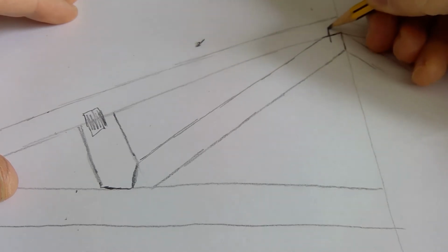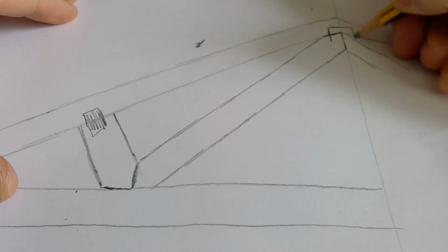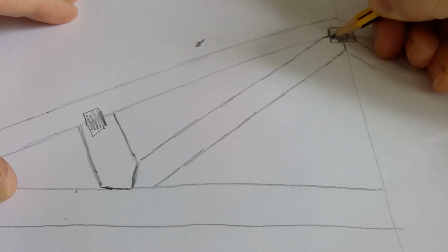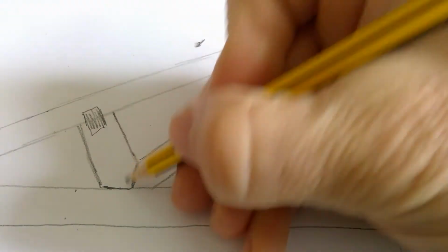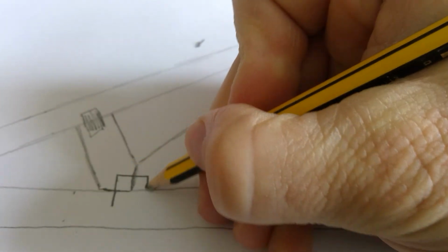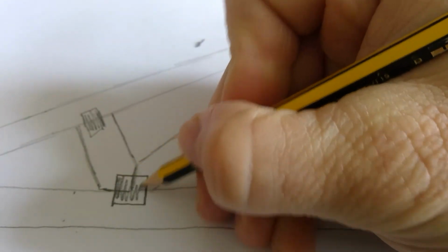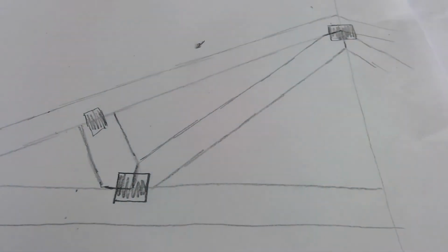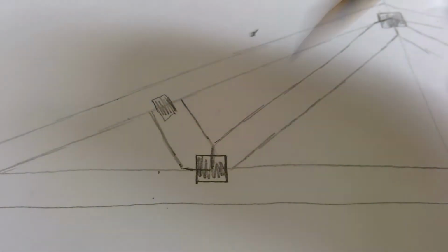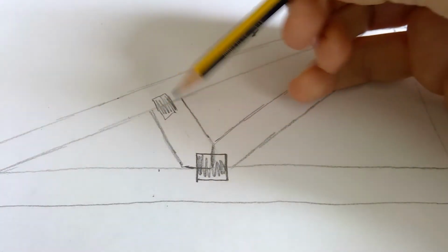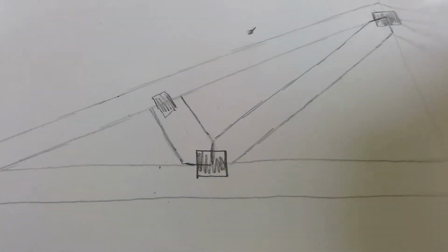Now there's a nail plate that goes into place like this. They have a bigger nail plate for these top pieces. Again, just simply look it up on Google if you want to get that understanding. That is there. And there'll also be a nail plate covering these three pieces here, which fixes it into place. There's a nail plate on both sides of those. Okay, so don't worry too much about angles and positions. If you get it roughly like that, you're going to be spot on.